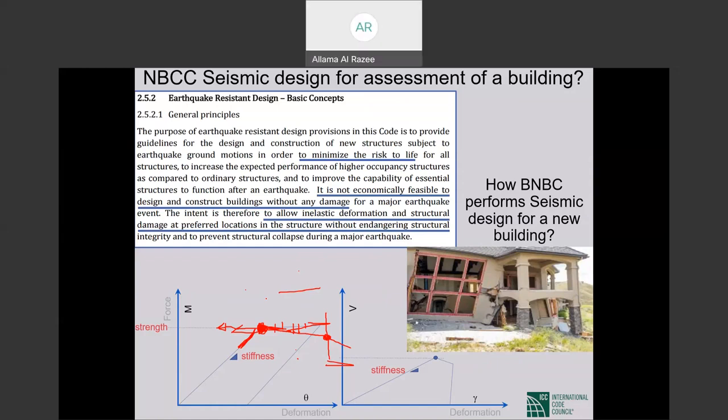The building gets damages. We should monitor each element and in each element, each response parameter, and see that none of them passes the ductility capacity of that element. So, for example, in reinforced concrete element, some behaviors, shear, for example, is very difficult to make it ductile.